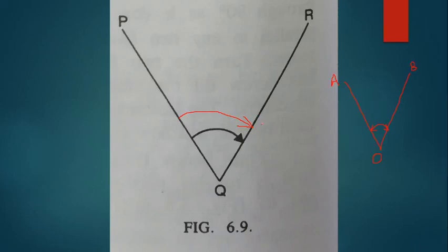Let us say with the upper tangent screw and upper clamp screw I have exactly bisected the ranging rod at R, with the instrument at Q for the second time. Let us say this is first and this is second time. Now the instrument is ready for taking readings again on vernier A as well as vernier B.